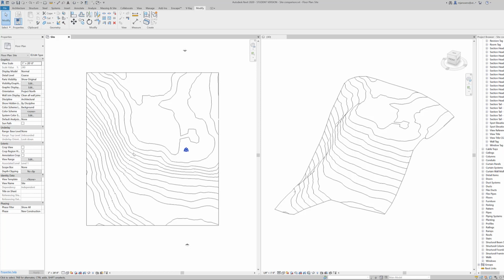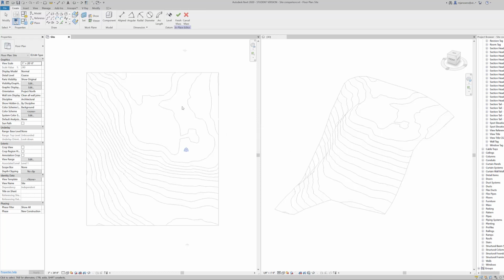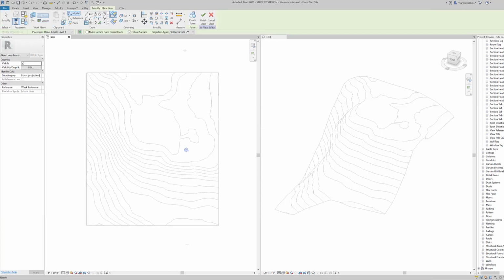So we went over an example in class of how you would create a divided line on the topo surface, and then you would populate that with a repeated shading element or whatever. And to do that, you would have to go into a mass and create a spline through points, or you can create it as points individually.